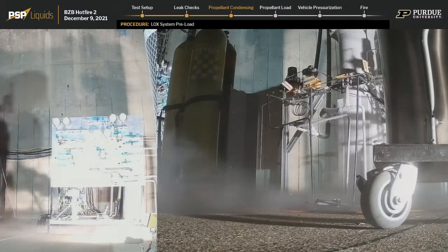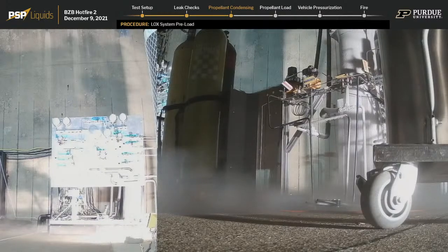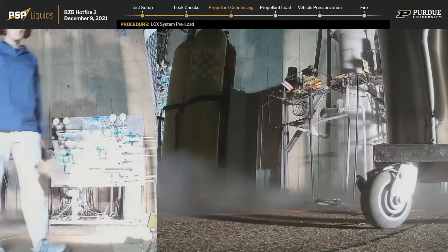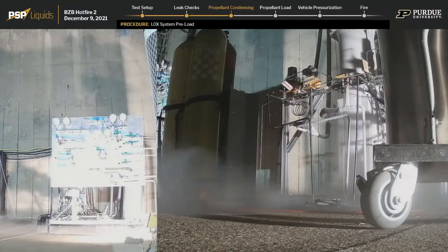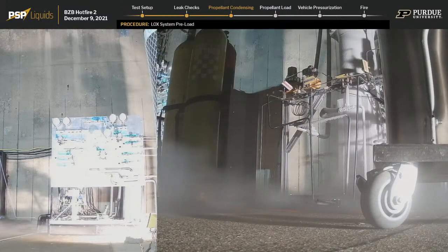The next thing we should talk about is why that random tube is coiled. If you see right under one of our valves, there is a coiled tube. What happens when you coil a tube, and what's the purpose of it? So when you coil a tube, you basically put a large amount of length between that and whatever's behind it. And so that results in a fully developed flow, and it also kind of isolates it from what's upstream in the system.